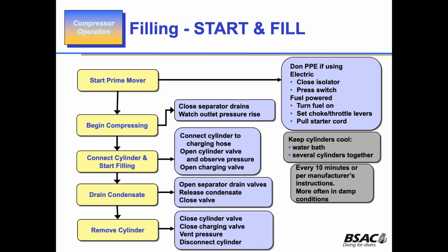You leave one of those drain valves open and you won't fill it. It'll get to a certain pressure, and depending on which drain valve you've left open, the pressure won't go up. You just quickly open it, and most of them are spring loaded, so as soon as you let it go, it closes.